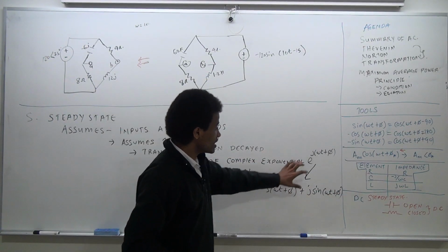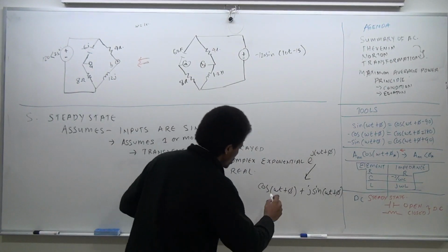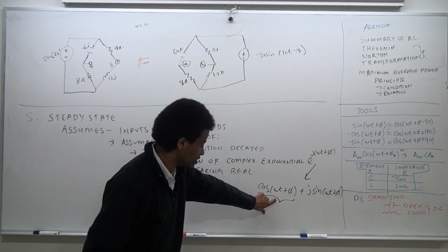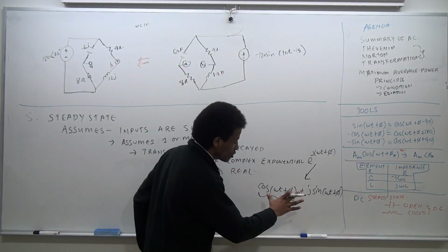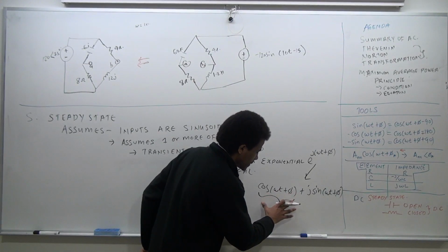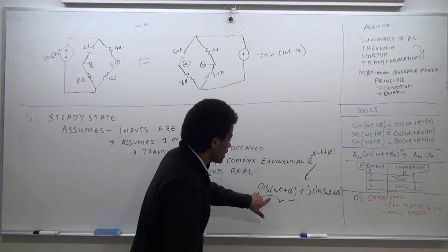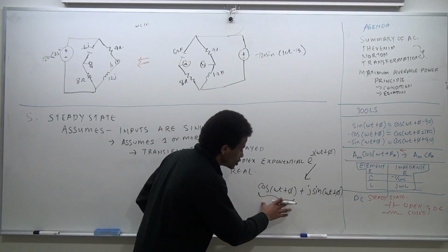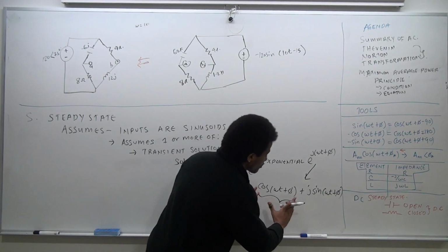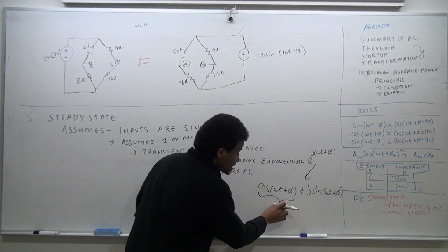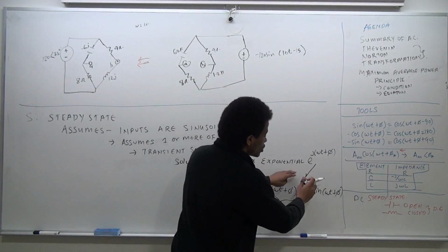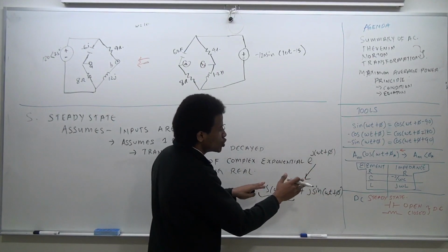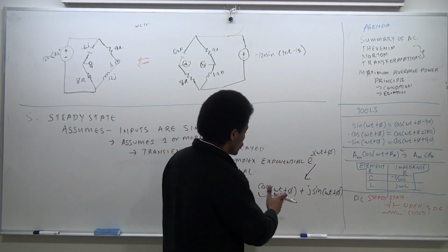Initially you were given an input. This is the real input that we initially have. This is what the problem gives us. The problem is we have a sinusoid as an input, for example, the voltage source or current source could be a sinusoid of this form. Okay, this is what we have. And the problem is you're saying we can't solve this easily, so we generalize the problem to include a complex exponential. So we are simultaneously solving two sort of orthogonal problems, one of the cos and one of the sine,